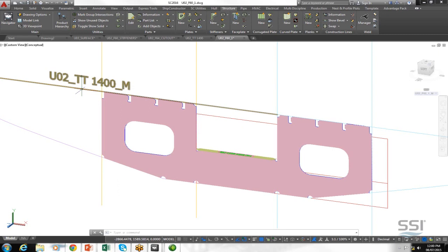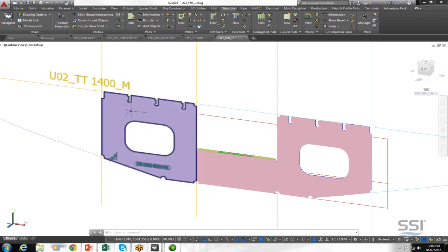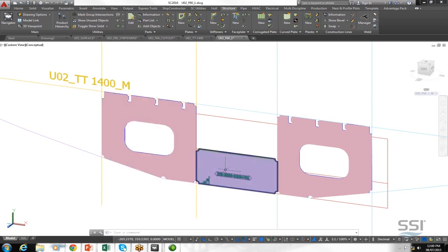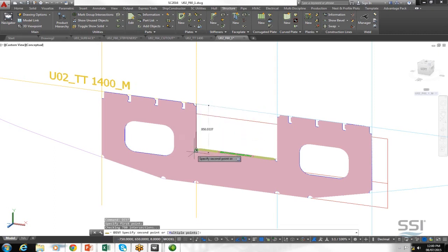Now as part of that, we also defined two of our plates based off of that construction line. So when the construction line moved, the plates have expanded to meet the new location of the construction line. Also, our central plate was defined as an offset of that planar group. So we should have, I think we settled on eventually 900 mils for that. So if we go down to this, and yes, it's 900 mils.